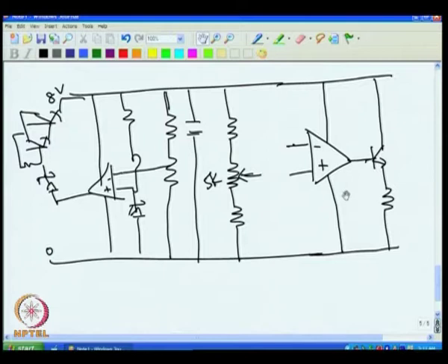So, what we can do is connect it so that an increase in this should increase the voltage here. So, obviously, we have to connect the output of the potentiometer to the plus terminal, so that when this increases, the output increases. But then we also want to make sure that the current does not go very high. So, we give the feedback here, we connect this to this.